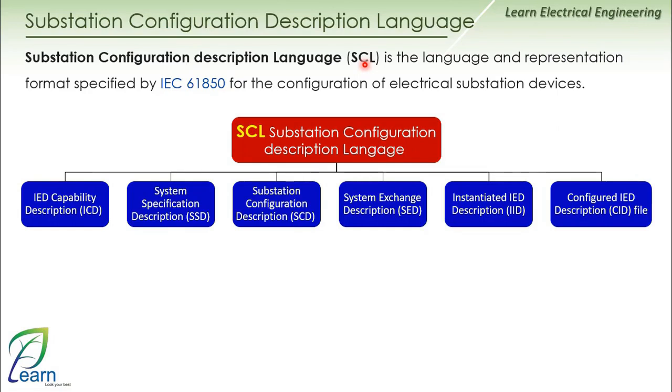What does this mean? For example, in GIS, when you have a section with a group of feeders, the bus disconnectors in these feeders need, as part of their interlocking, the status of the bus bar switch. The bus bar switch is located in the bus section panel, so instead of running a wire to reach all the panels, if you have 10 panels, you would need 10 contacts from the bus bar switch to connect them to the 10 panels. If you used cabling and different contacts, it might not be available to you. Why not use a PCU to PCU connection to the other feeder?